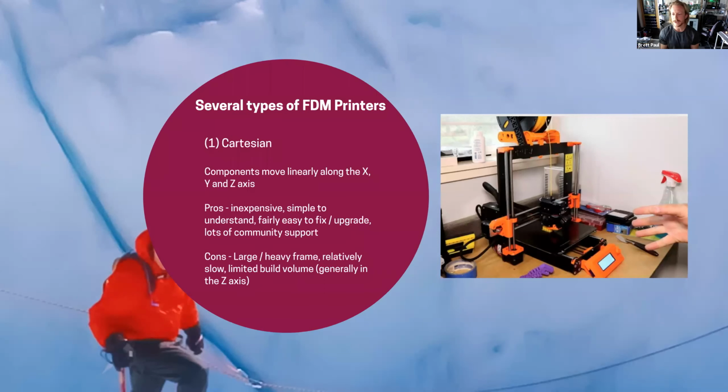You're constantly fighting the temperature of your filament, because sometimes you want it hotter in some places and colder in others. Experimenting with fans and troubleshooting to get the type and quality of print that you want can be kind of cumbersome. So I would add that also as a con to this particular type of printer.